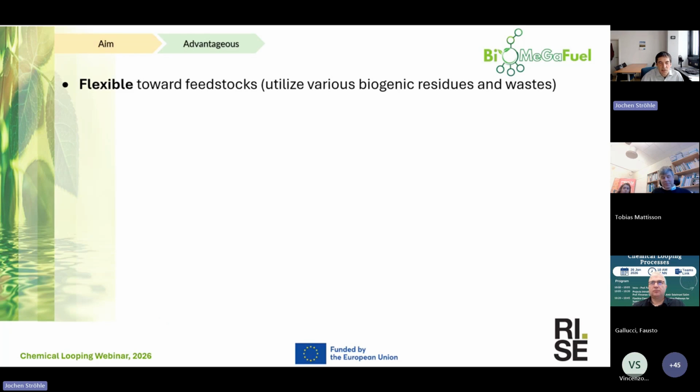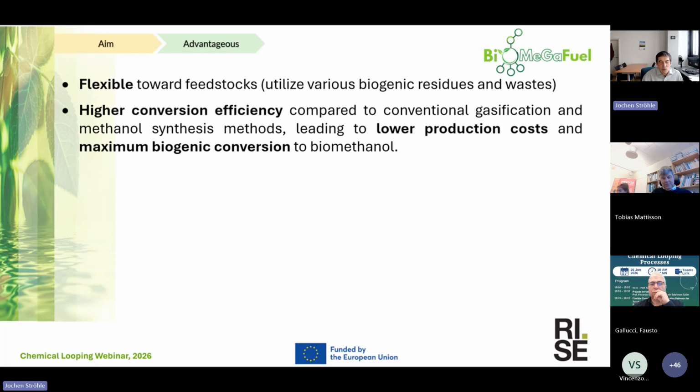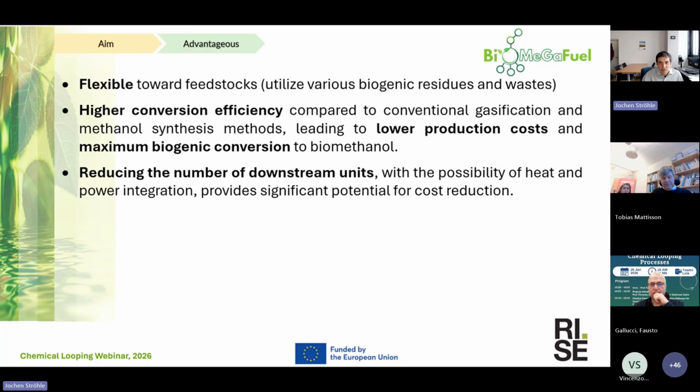The advantages: we are flexible towards feedstocks, utilizing various biogenic residues and waste, since it's a fluidized bed technology. We have a high conversion efficiency, higher than conventional gasification, and methanol synthesis leads to lower production cost and maximum biogenic conversion to biomethanol. We are reducing the number of downstream units.